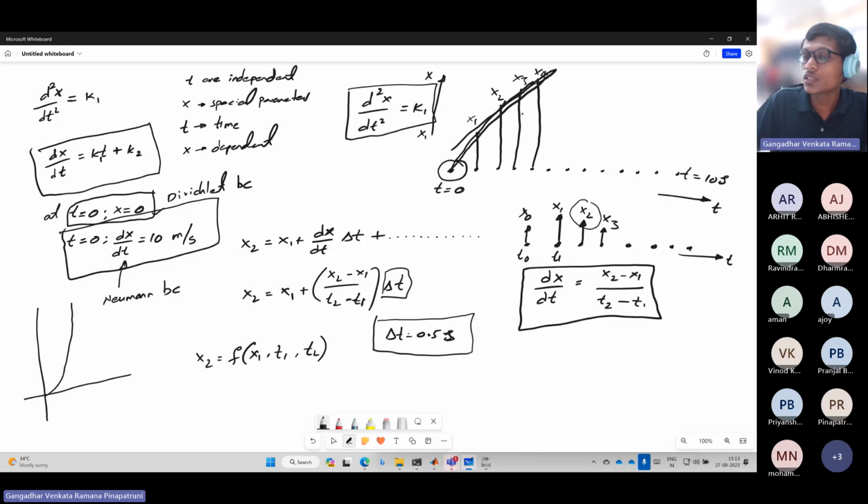So this is the concept behind why we are creating the domain, why we are splitting it into small cells, and the importance of mesh size. Why are we solving the partial differential equations? For understanding the solution. Partial differential equations are derived based upon laws. What are those laws? Mass conservation, energy conservation, and momentum conservation. Those are the governing equations. So the governing equations are in partial differential form.